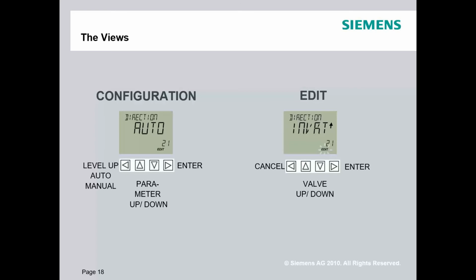Now, the piezo block is 2 screws. It can be replaced. If you fill a PS100 or our PS2 with relatively clean water, which I'm not sure I've ever seen too much, but if you fill it full of water, most of the time it will dry out and go back, it'll work. Now, if you fill it full of compressor goo, oils and all that stuff, it's done. Okay. Clean air I like.